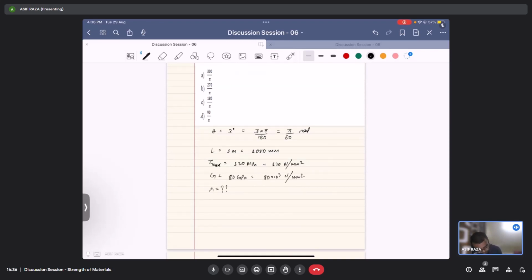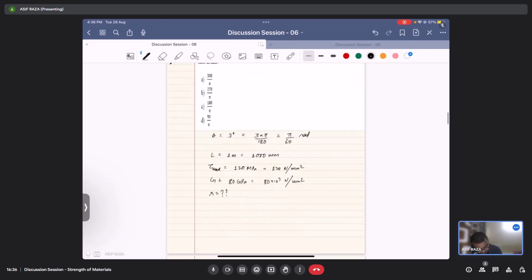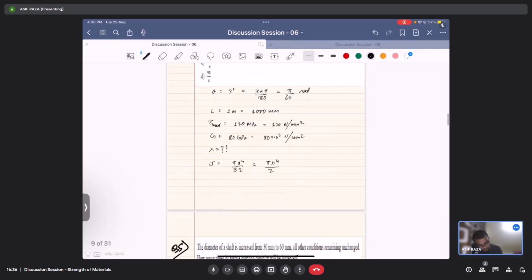So for this kind of question, my polar moment of inertia would be pi d4 by 32, or I can write pi r4 by 2, in mm4.